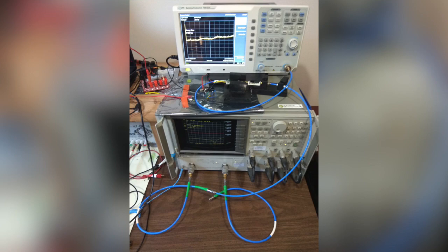So for the spectrum analyzer, some general considerations: you need to figure out all the front-end attenuation ahead of time. Here we've set the RF attenuation to 0 dB, and it has an internal preamp. You want to enable the internal preamp. And then on top of that, you need to add some external preamps, which are shown over here.